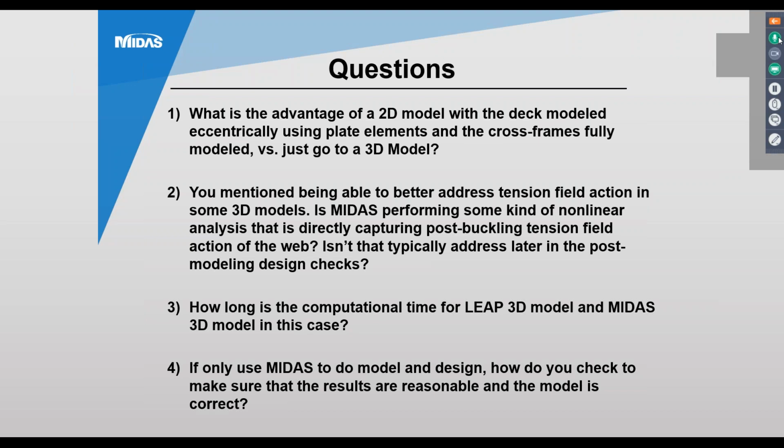Girder lines don't take long, the V-load doesn't take long. At minimum, do that. You don't necessarily have to do what we've done here with these extra finite element models. I'd say that's a best practice, but of course, we don't always get the fee to do that kind of modeling. And as fees go down and we're trying to be more efficient, you might see that you couldn't really do that full thing, but at least get that girder line in there. You definitely don't want to use just a finite element model. So hopefully that answers those questions.